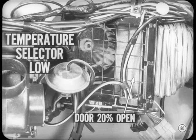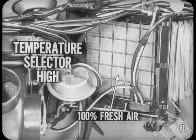Disconnect the solid black vacuum line at the water valve thermostat. This is the control vacuum line. Set the temperature selector at the lowest point and press the auto button. The door should move to the 20% open position. Reconnect the vacuum line at the thermostat and move the selector to the highest heat position. This should move the fresh air door to the fully opened position. If any of these positions is incorrect, replace the transfer switch.